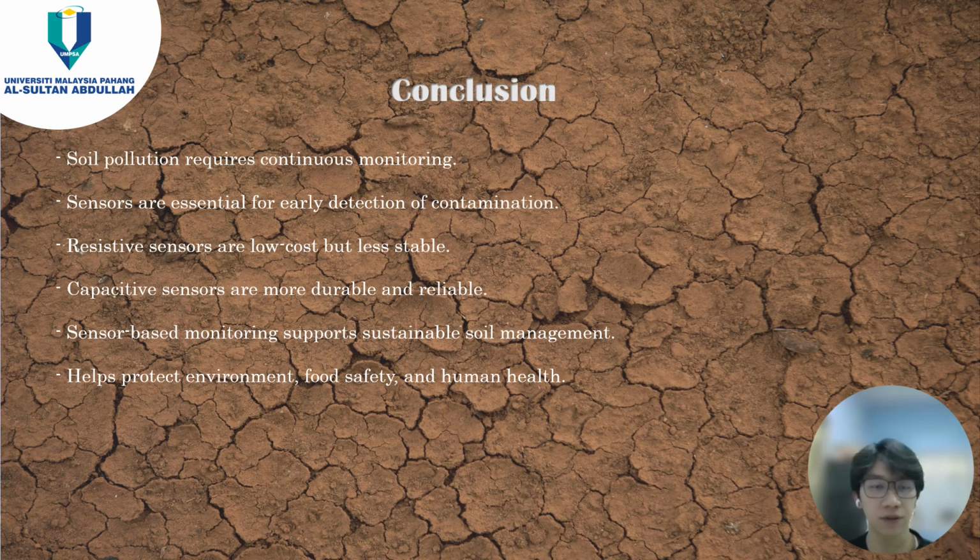From today's presentation, we can conclude that soil pollution requires continuous monitoring. Sensors are essential for early detection of contamination. Resistive sensors are low cost but less stable, while capacitive sensors are more durable and reliable, especially for long-term projects. Sensor-based monitoring supports sustainable soil management, and it helps protect environment, food safety, and human health.